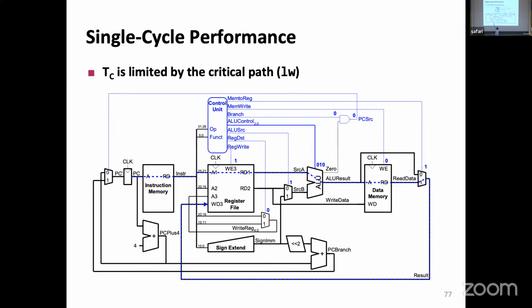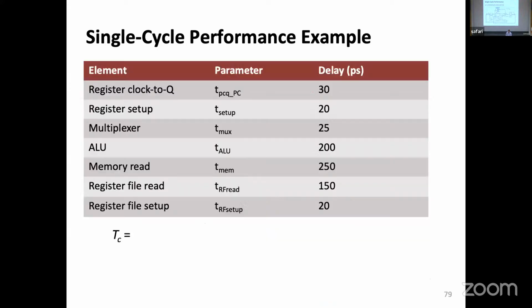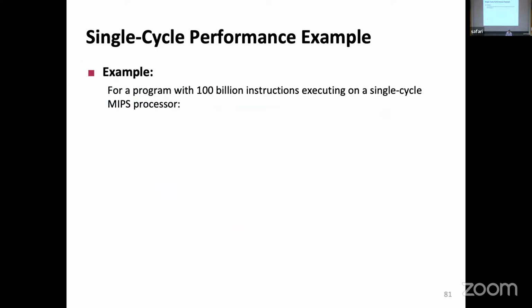There's also one path that, for example, starts from here, goes through this program counter, comes back, goes through the multiplexer and writes back. However, I told you, additions are long, multiplexers are short, but this one has memory, addition, memory, mux. No comparison to a single addition and memory. But knowing your path is one of the issues.